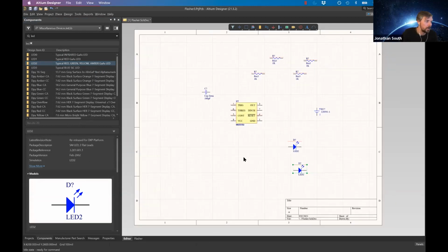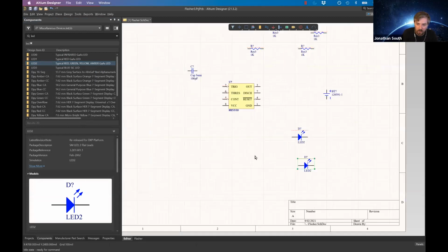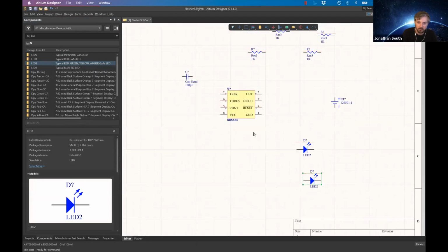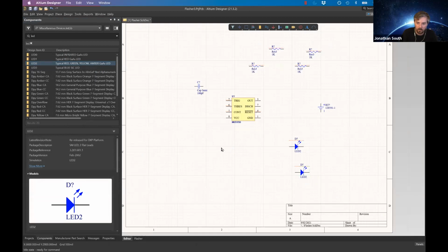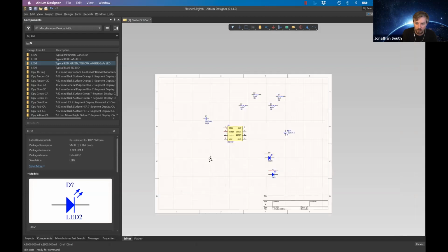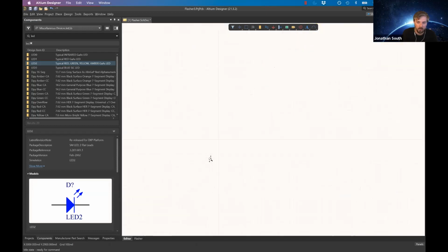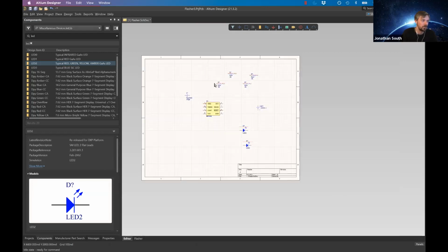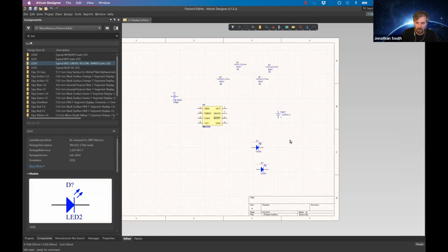Yep, so how do we drag and move the schematic sheet around? Right click will do the pan. I think Control Scroll for me does zoom in. And yeah, you can obviously do box select. I think clicking my middle mouse wheel also does a zoom in and out as well, but control scroll I have a bit more control over. Some of these shortcuts and key commands are reasonably similar across these sort of programs, but sometimes they just make slight changes that just screw you up.